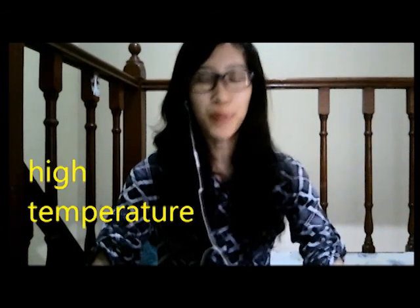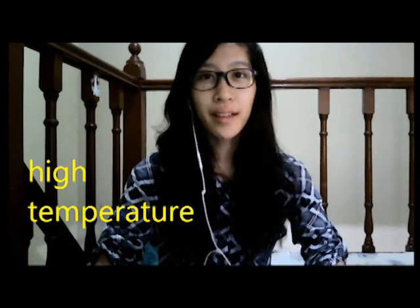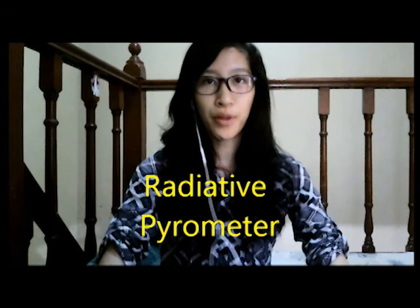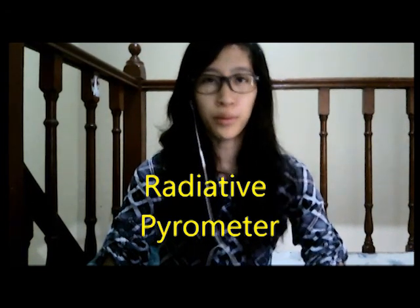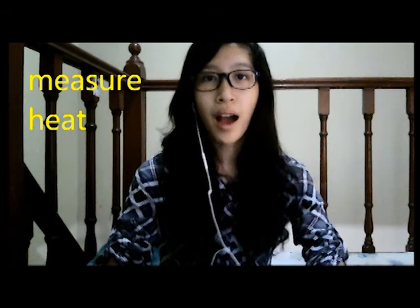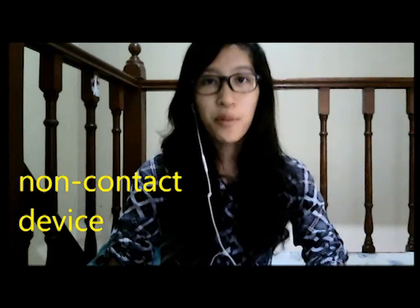When the temperature to be measured is high and physical contact with a heated object is impossible, radiative pyrometers are used. So, what are radiative pyrometers? These pyrometers measure the heat emitted by a hot object, and it is also a non-contact temperature measuring device, used under conditions where corrosive vapors or liquid would destroy a thermocouple, resistance thermometer, and thermistor.